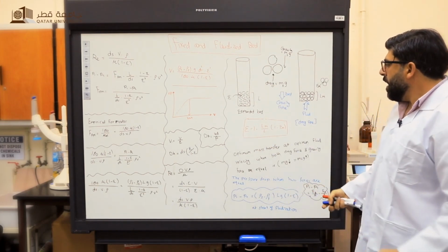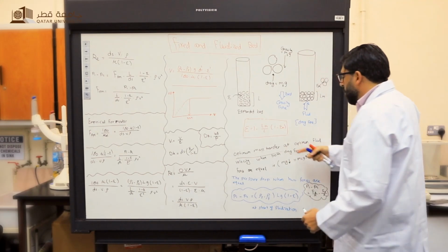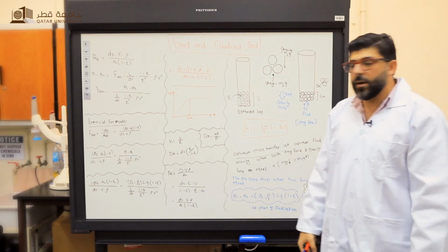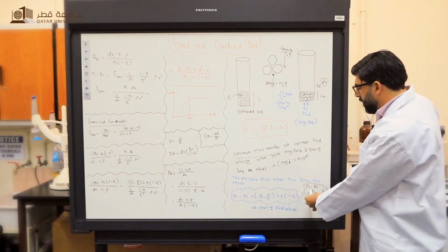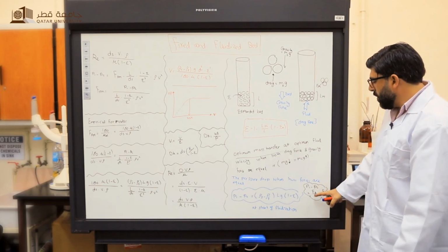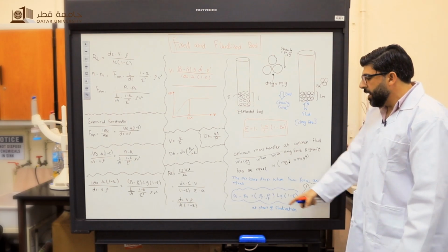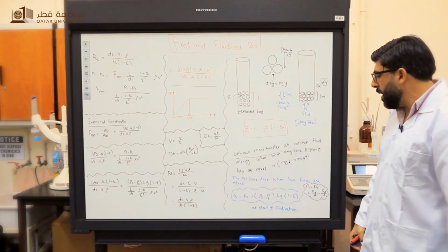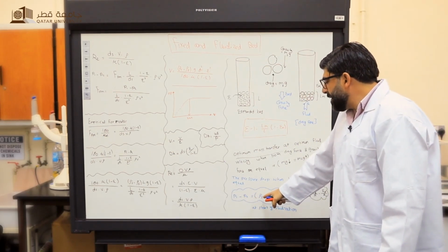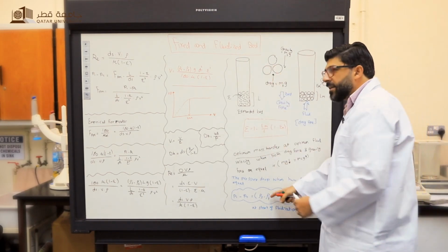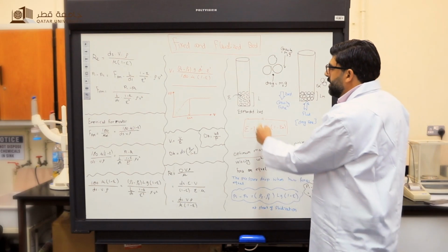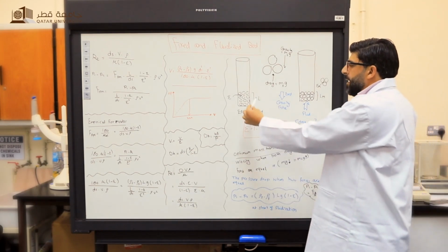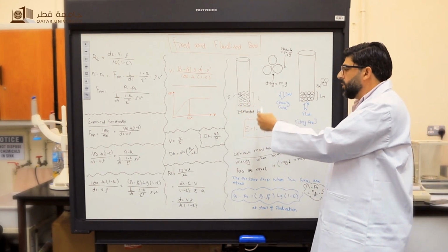So the optimum mass transfer will be at the optimum fluid velocity, when both drag force and gravity force are equal to each other. Pressure is force over area, so we have gravity force minus drag force, over area. When both forces are equal, the pressure drop is P1 minus P2, equal to the density difference between the solid particles and the fluid, times L, the height of the bed, times g, the gravity, times 1 minus epsilon. Epsilon is the spaces between the particles, called porosity or voidage.